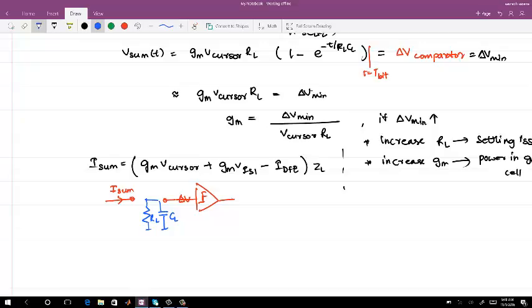Oh, sorry, that's the load. That's not the current. This is only the current, and it's just stored as a voltage. So this is the current which is going into the summing node. The way I created it previously, I passed it through a load resistance and got the voltage. But CL comes on its own and I land up in a settling issue. So what is the other way you can think of generating a voltage, delta V, using a current?